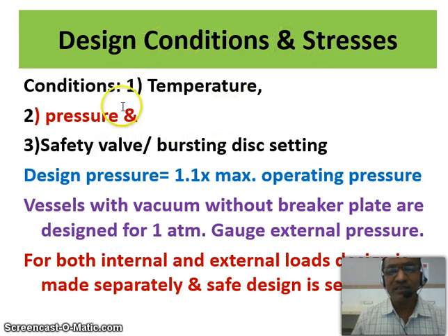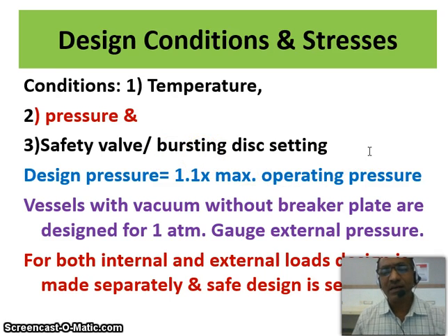In all the equipments, to ensure safety, it becomes necessary that they are fitted with what is called a safety valve or a bursting disc, which are set as per the design pressure values and the temperatures. The value of the design pressure for design calculation always has to be taken 10% more as compared to the maximum operating pressure of the equipment.